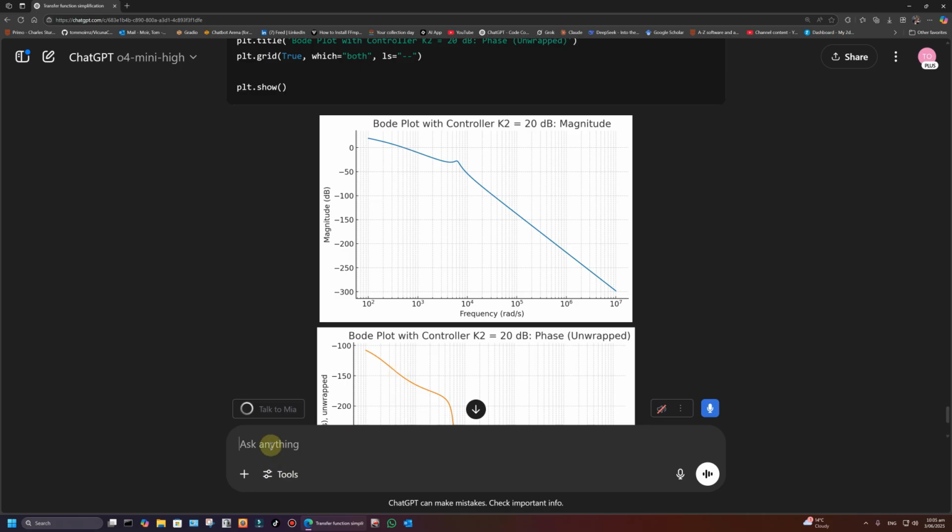So if I tell it to do a closed loop system around this, it should be stable, but it'd be quite oscillatory, because its phase margin is only 30 degrees. So it should have something like 30% overshoot of that order. Determine and plot the closed loop step response again.